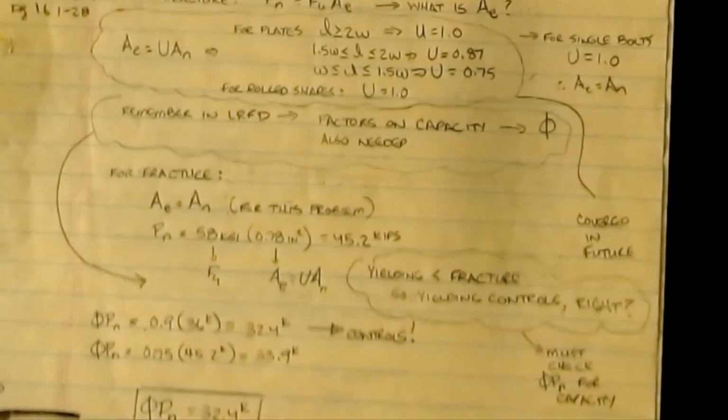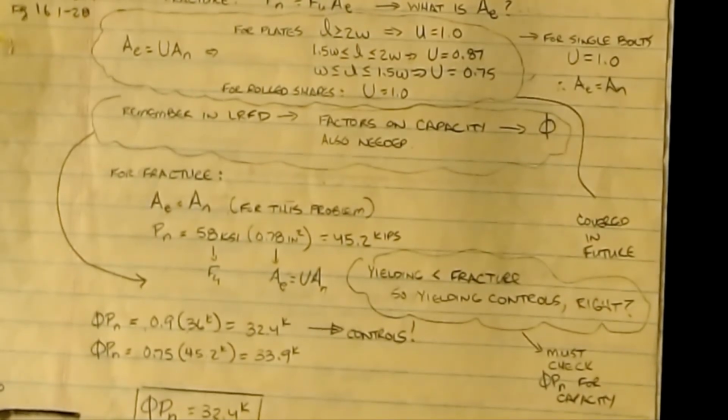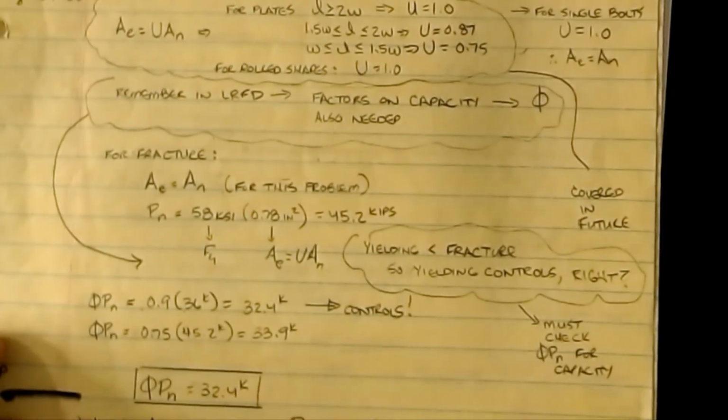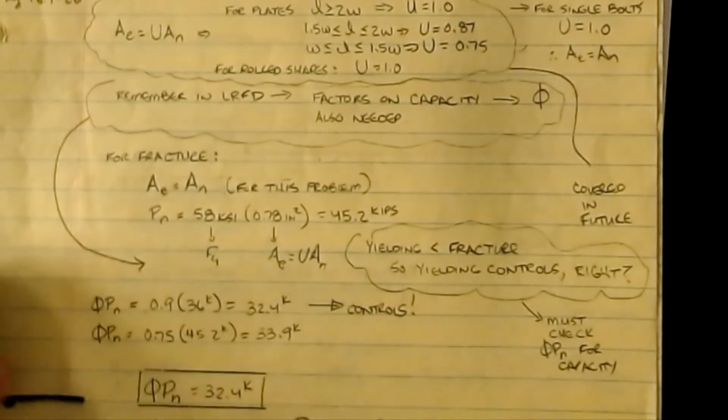Again, remember your holes. Remember to add your oversize. Is it a standard hole? Is it an oversized hole? Is it a slotted hole? Make sure that you add the 16th for damage. Typically, we just add that to cover the case where it's punched. If it's drilled, well then the connection's stronger than what you're expecting it to be. It's just conservative to assume that it's always punched. For this class, I'm cool with that as well, unless I specify otherwise. Those are all some basics into designing tension members. Again, there are some other things we have to consider, and we'll do that in the next video.